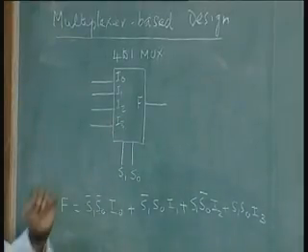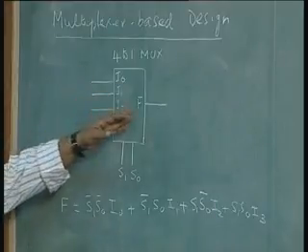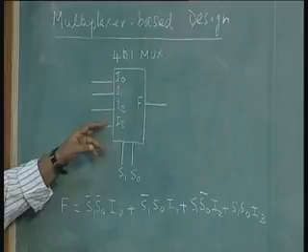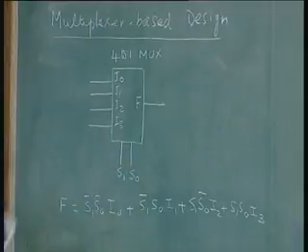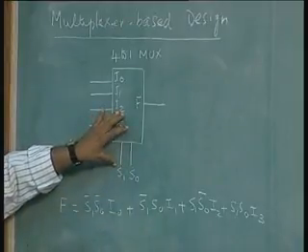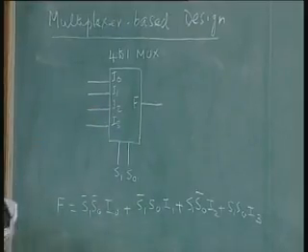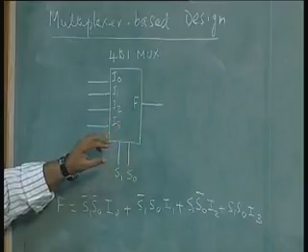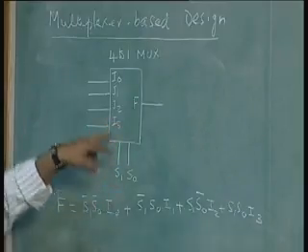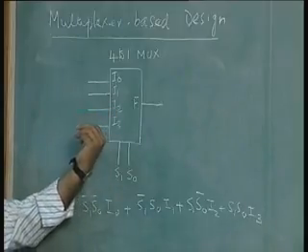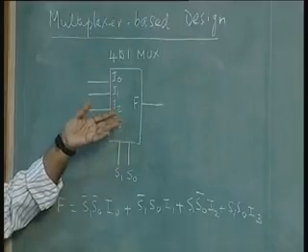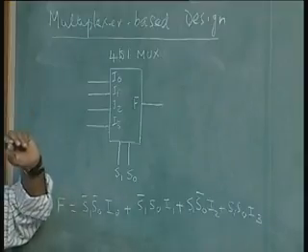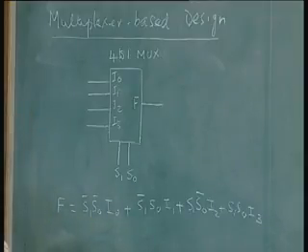This is a multiplexer which selects from a given number of inputs one of the inputs as the output, and the output selected depends on the selector combination. Now, I can use this component to design a logic, combination logic. Now, this is not a gate approach, but it uses gates because you know that a multiplexer cannot be built without gates. If you break into the multiplexer and see what is inside, you still will find AND gates and OR gates. Like any other combination logic, everything can be reduced to a basic set of AND OR inverters or a universal gate such as a NAND gate or an OR gate combination.